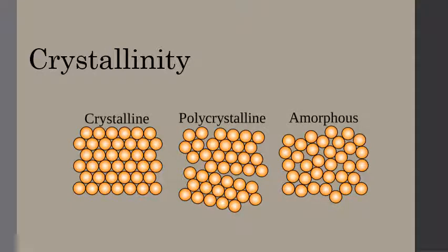Polypropylene and plastics are different than most materials. It is not crystalline in structure, but is rather amorphous. This means that the material might have a defined shape, but it lacks the order and organization that crystalline materials have at the atomic level. Most industrial polypropylene is made up of 30 to 60% crystallinity. The rest of the polypropylene structure consists of amorphous properties, allowing the material to flex and bend under stress.